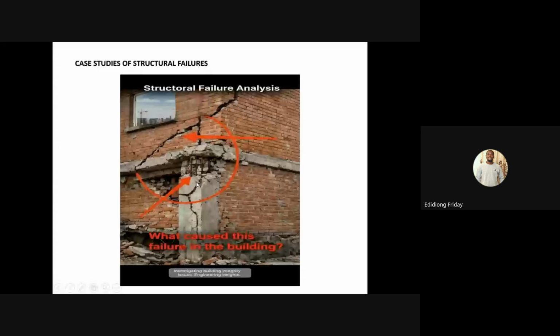Now for the remedy for this kind of critical case, I would suggest complete demolition of this area. You demolish the partition walls, then continue the column, and also check for any adjoining or close column. Either introduce a ground beam or carry out underpinning in order to tackle the differential settlement of this column.